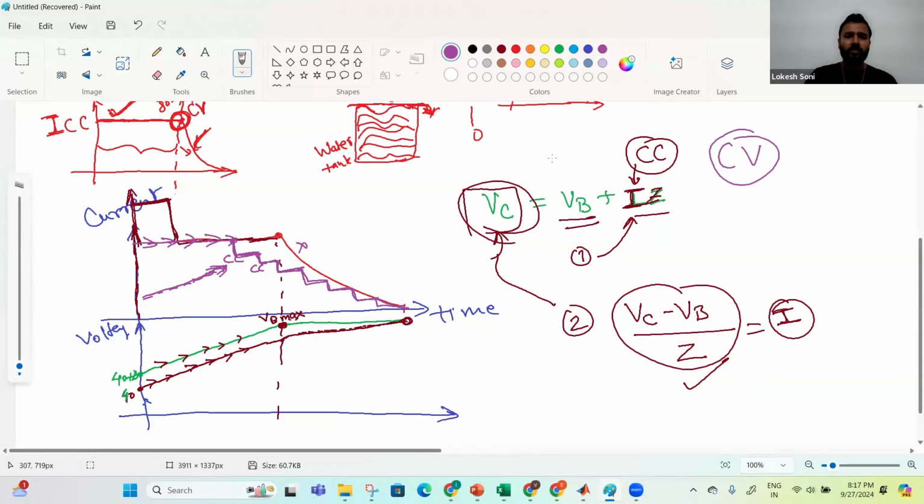I already told, boost charging has its own reasons, so it depends on the requirement. If some battery is having active cooling on it, probably you would not care about the temperature based effect on the health. So it depends on what the requirement is, and what kind of battery it is, chemistry, and cooling wise and stuff. Okay, so fundamentally this is what is happening in terms of voltage and current.